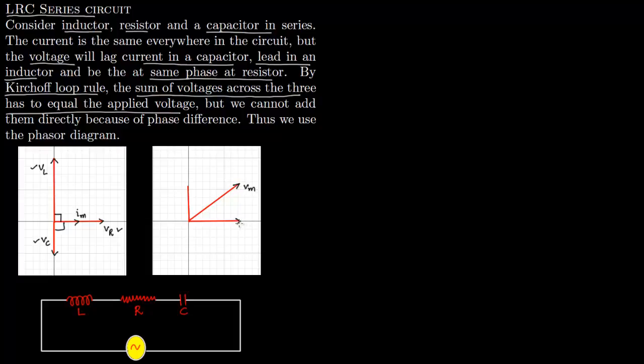So again we will have this voltage across resistance here, and now this vector is nothing but VL minus VC. Now we can see that this vector Vm is sum of these two vectors, VL minus VC and VR. So this is what this voltage vector is, and therefore the length of this vector by the Pythagoras theorem, this is hypotenuse and these other two are sides of a right angle triangle, or the length of this vector is nothing but VR square plus VL minus VC square.